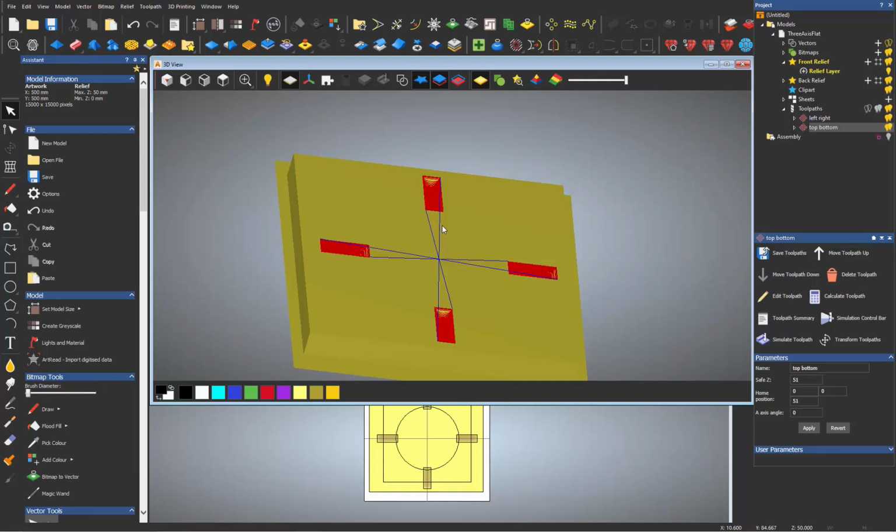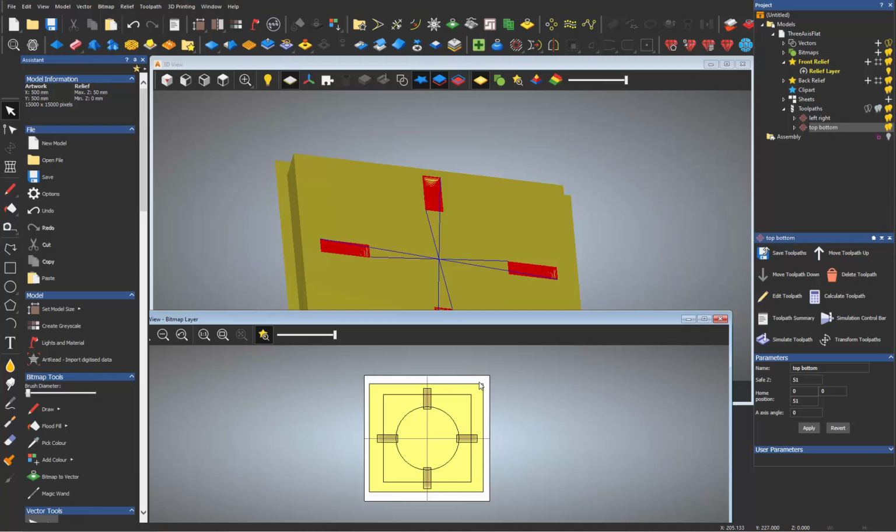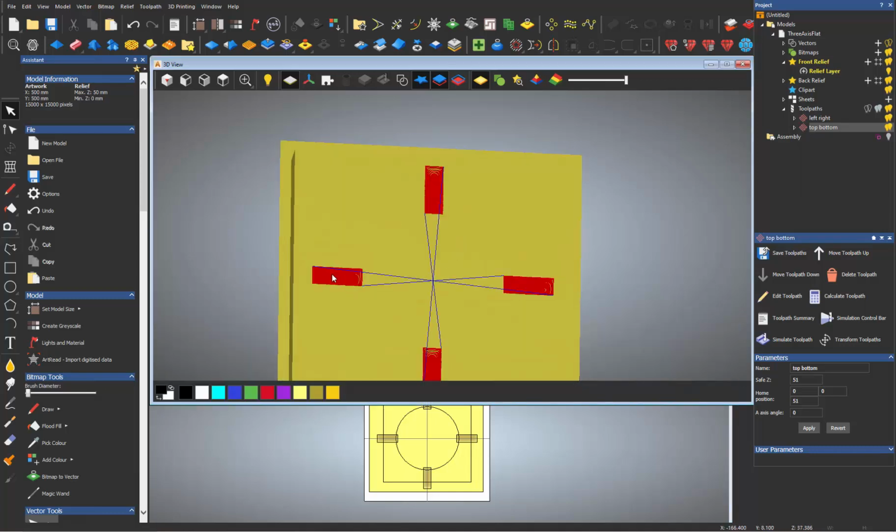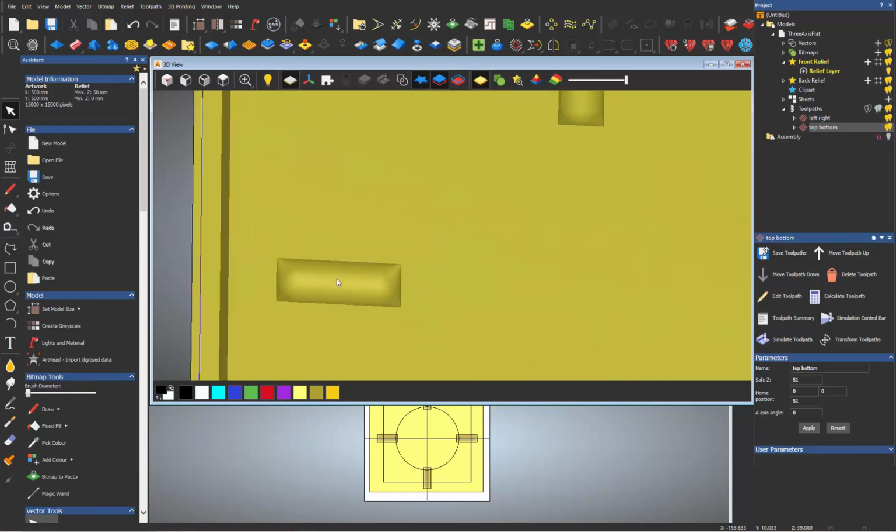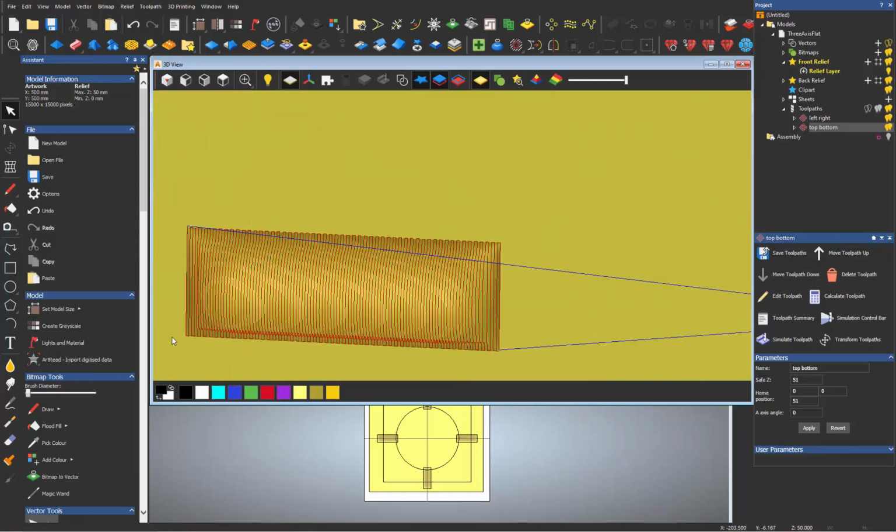You see there's no center hole, and I've got my outlines here, and you can see that I've made a piece of material. This would be his actual piece of material here, but I made this larger. When I create these toolpaths, I had to group these together and these together because I'm rastering with the grain in this direction, and I only have a finish, but you would want to do a roughing toolpath and leave a little skin there so you can do a really tight, nice finish pass. I'm not going to model that.